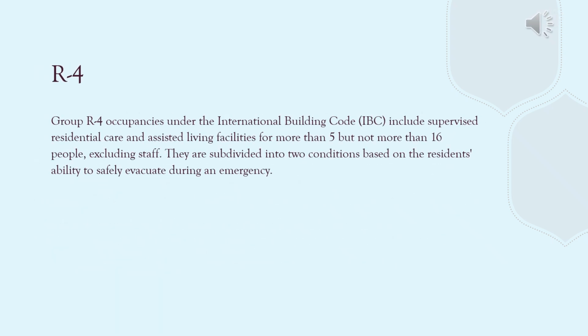R4 occupancies under the IBC include supervised residential care and assisted living facilities for more than 5 but not more than 16 people, and this excludes staff. They are subdivided into two conditions based on the resident's ability to safely evacuate during an emergency.